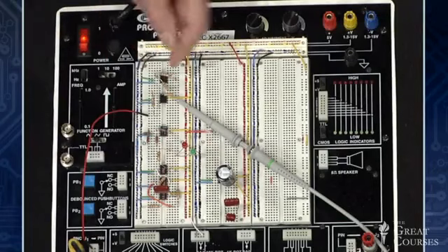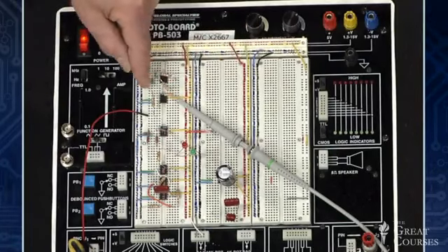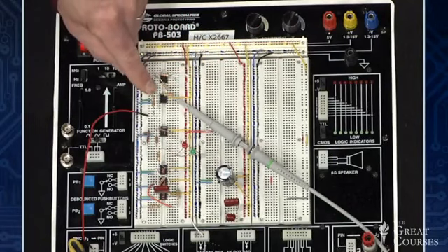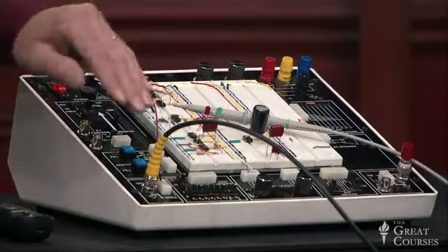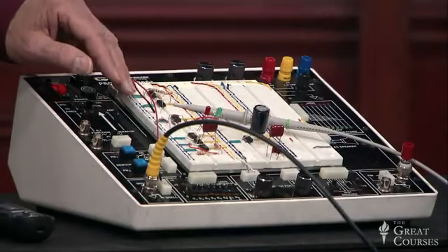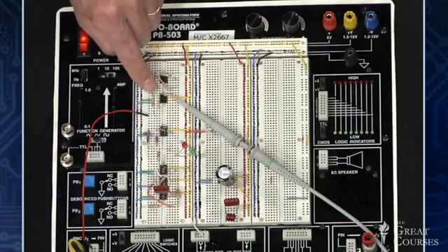So here's the op-amp. The output of the op-amp is over here. The output goes back through that 33 kilo ohm feedback resistor to the input to that first op-amp. The input resistor feeds in, and here's the input signal coming in from our function generator. This time it's a 1 kilohertz signal. The input resistor and the feedback resistor join at the inverting input of the first op-amp.